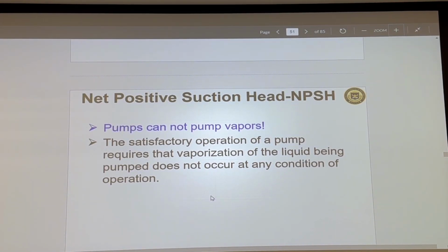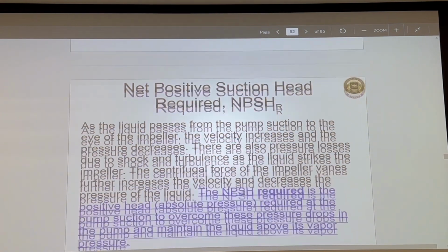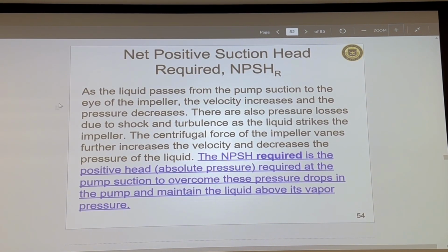I'll tell you, especially with a gas pump, when you go to higher altitude, the water or gas evaporates much faster. That means the suction is another issue. So your pump should be able to handle those conditions. That means you should design in such a way that the pressure won't drop down to that of the saturation pressure of the liquid. He's just giving some examples, something to read and remember.